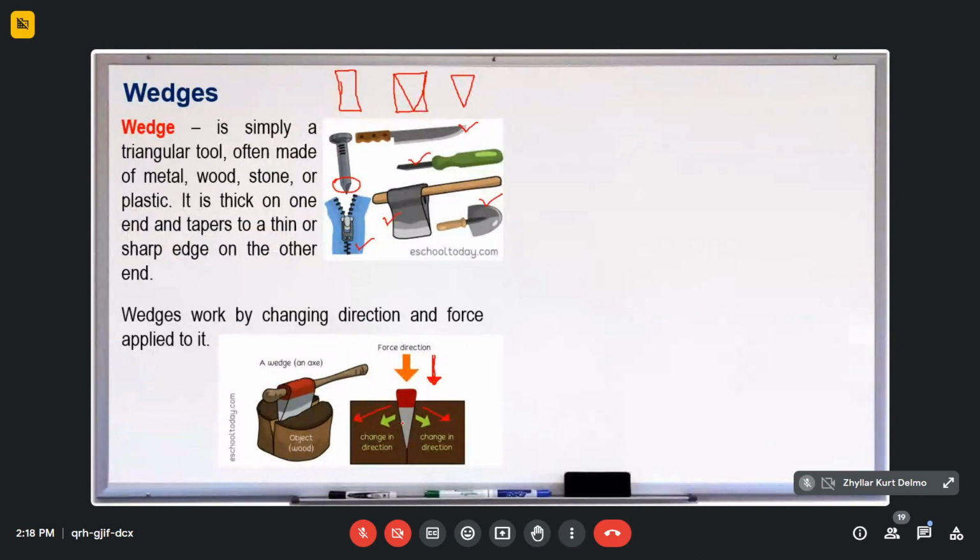If we have enough friction between the surface of our axe and the surface of our wood, we can create a bigger force that will split the object into two equal parts. But if it slides, what will happen? If it slides, it cannot perform its task. It cannot split. So later, when we analyze wedges, we will see that it is very important to maintain a desired frictional force between the two surfaces in contact with the wedge. Okay, so this is how the wedging action works.